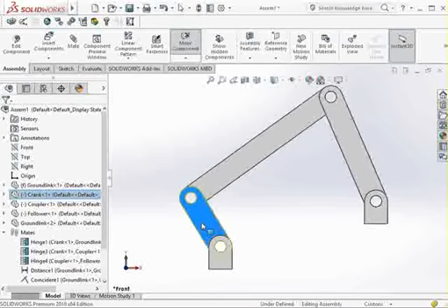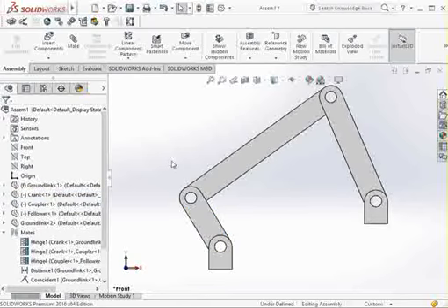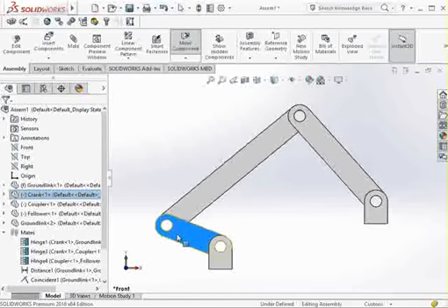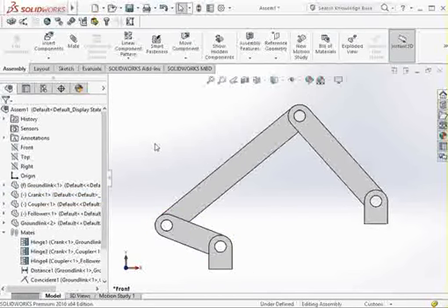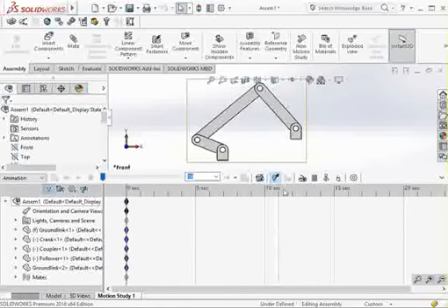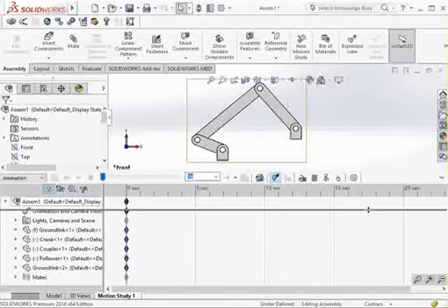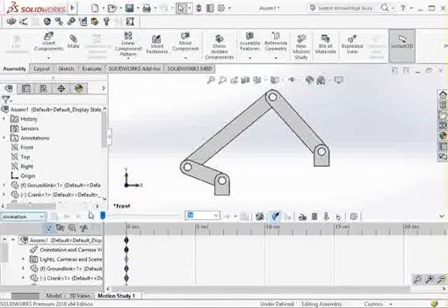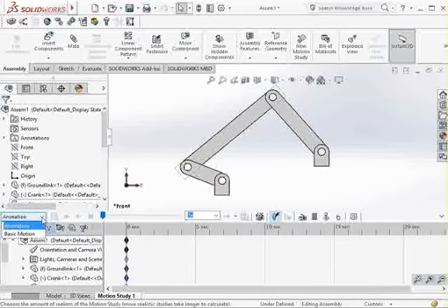So we've done this now. The next thing for us to do is to do a kinematic analysis, and then we'll come here, which is our motion study. See all the things we need. Remember that without activating the SolidWorks motion analysis, we'll be able to do just 2 basic things here: animation and basic motion.